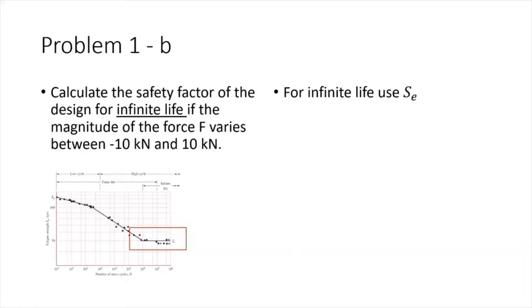This time, we can find the fatigue strength easily as it equals the endurance limit of the material. We also know the applied stress, so again, if we plug these values into our factor of safety formula, we find that the safety factor equals 2.